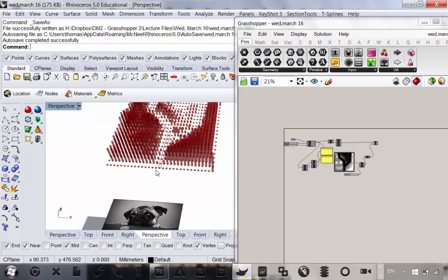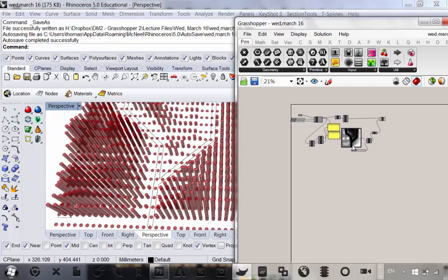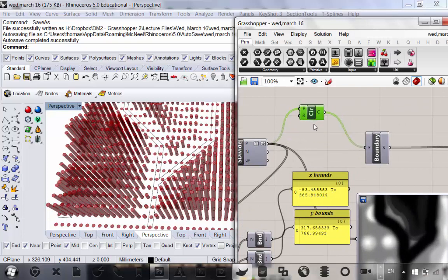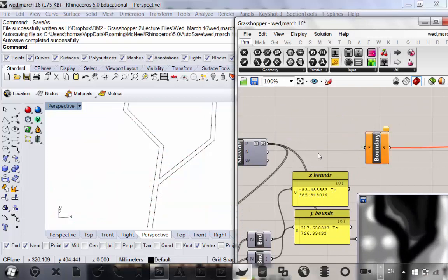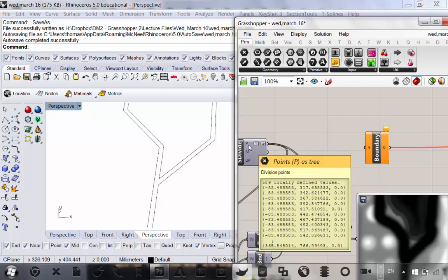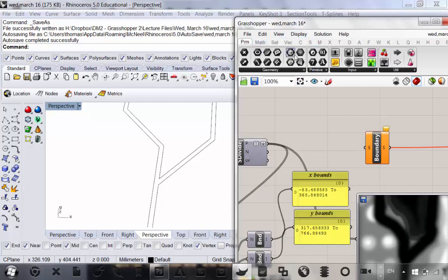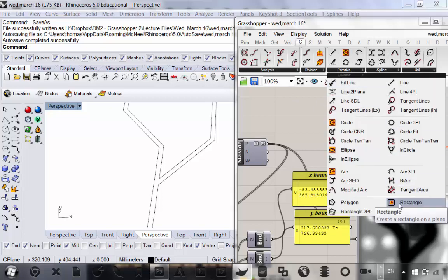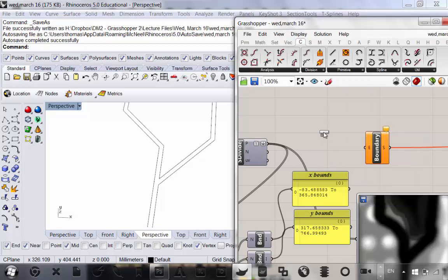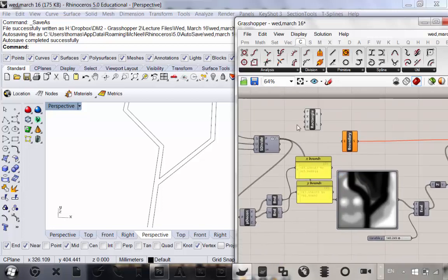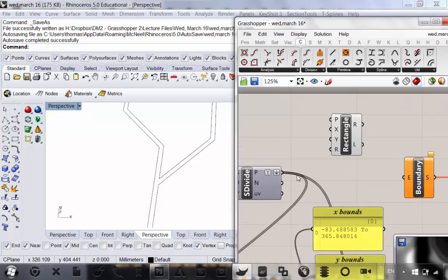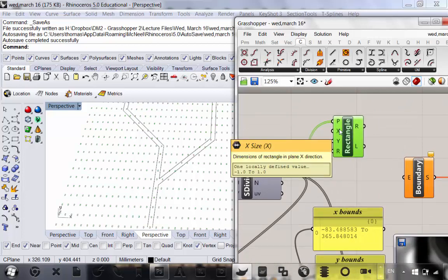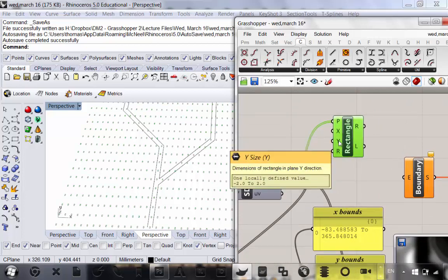Now to something that we can play around with a little bit more. So I'm going to change it to a square. All we're going to do is delete this circle, like so. And instead of the circle, we are going to go to Curve, Primitive, Rectangle. Like that, and we're going to put our points in. Again, rectangles have domains, like so.